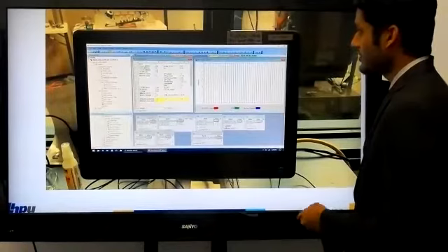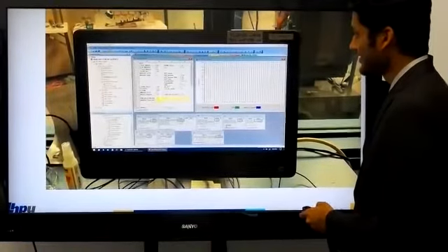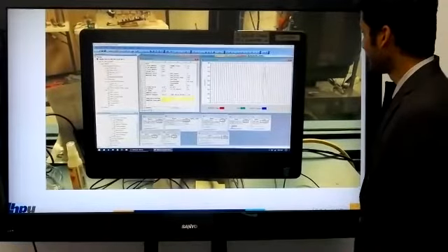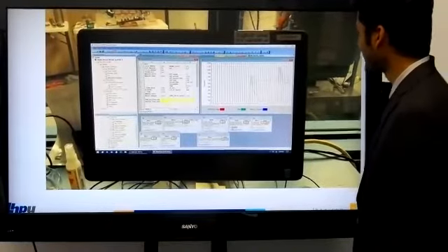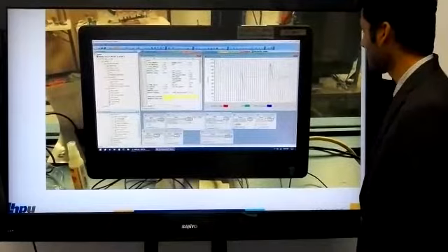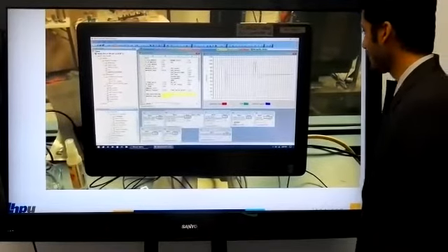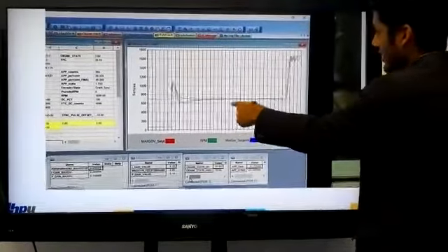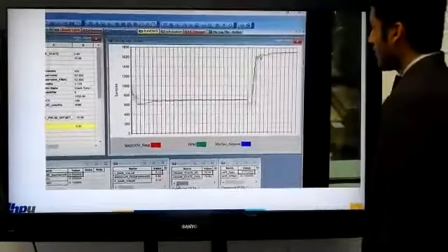This is a video of us running the live engine. The first time it didn't start. As we calibrated the P and I gains of the minimum governor, it is running very smoothly in the min-gov state.